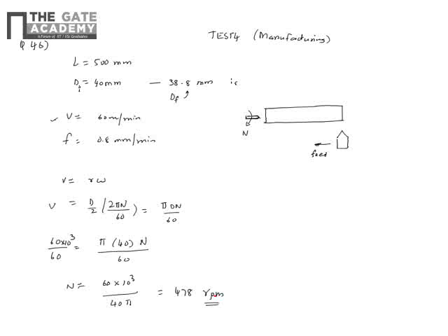in rpm. Now the turning time is basically, I need to cover this entire length, because in one revolution, if I just keep the cutting tool here, in one pass, it will reduce the diameter from 40 to 38.1. But now I have to cover the entire length, and feed is basically the axial movement, how much the cutting tool moves, that is 0.8 mm per revolution.